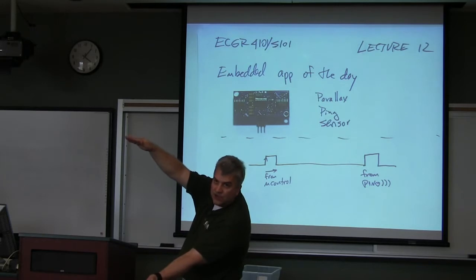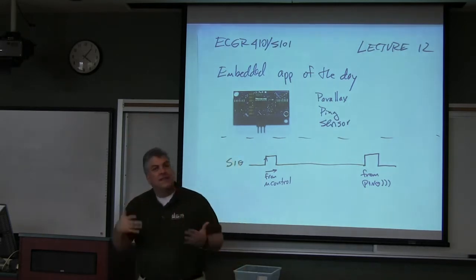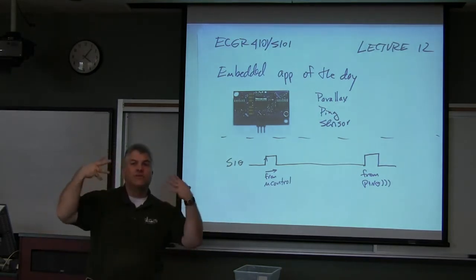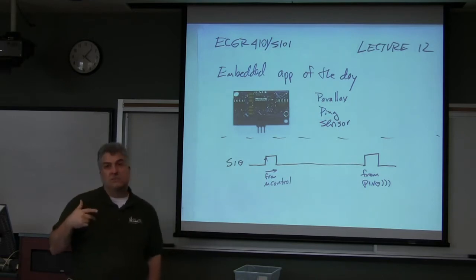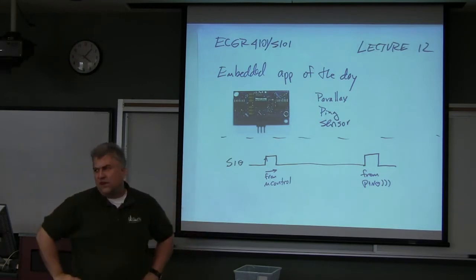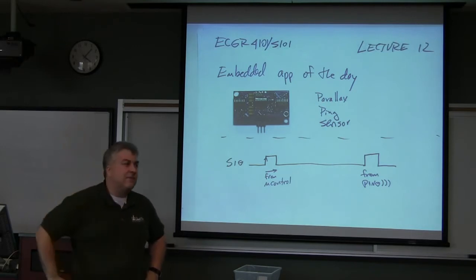And of course, as that range gets bigger, the energy dissipates some. So it's looking for a big bulk of something that will reflect the sound energy back. If it doesn't find it, it'll time out. I think the range of this is 30 feet, so after about the time that 30 feet would occur, it just says, I give up, there's nothing out there.